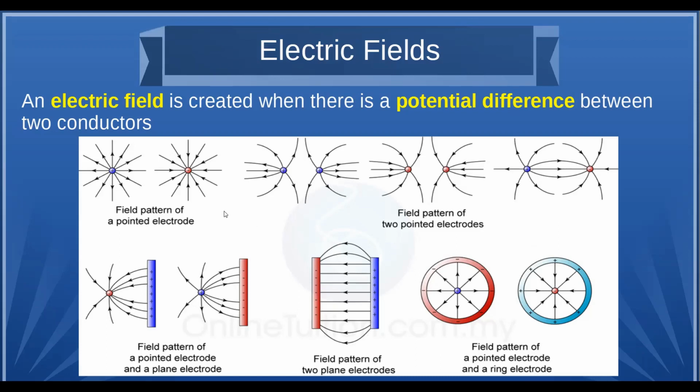Somebody got the bright idea, instead of having two wires side by side, which, like we talked about, you twist to reduce interference because they're susceptible to outside interference from other fields, that if you took one of those and wrapped it in an insulator, made the other into a sheet and wrapped it around, you'd contain the electric field within it. So it's not affected by any field from the outside, either magnetic or electrostatic. And that's how the coaxial cable was developed. So regardless of the polarity one way or the other, you've got this field contained within there.